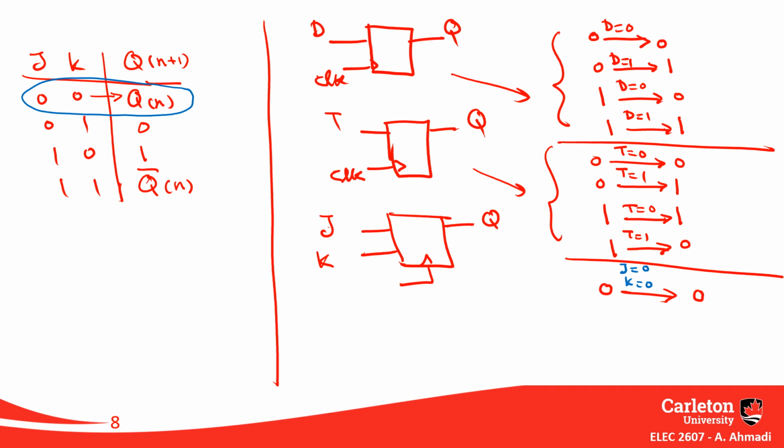Well, having said that, there is another combination of input which does the same for you. Look at the table. You want to have 0 after all. One way is, since your current state is 0, to apply 0 0, which won't change the state, you'll get 0. The other choice, however, is this one.